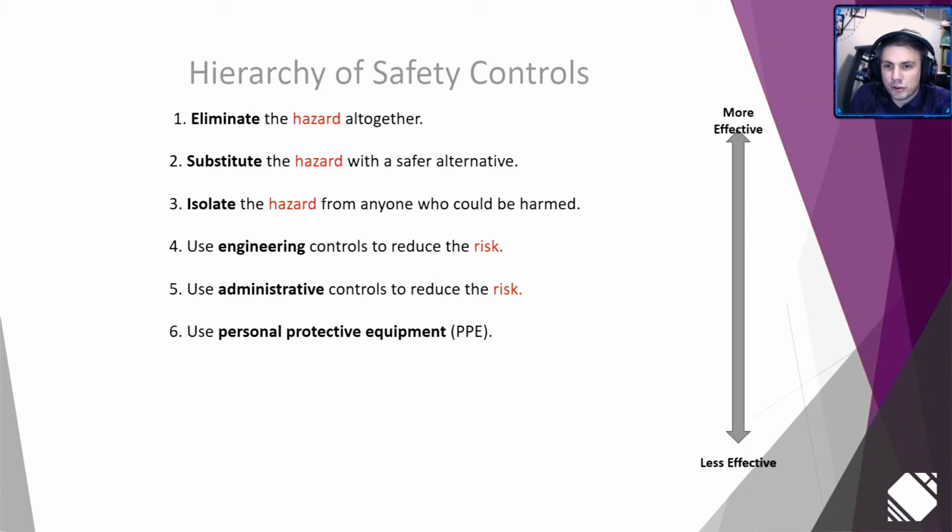And the last one is personal protective equipment. Something we do as engineers is called an arc flash study. You'll analyze the amount of energy potential inside of an enclosure so that if somebody's working in there, they know that they could be exposed to a certain amount of calories, it's called, which is just a certain amount of energy that could be blasting. And based on that, they know how much protective equipment to wear. The default being cotton clothing head to toe that's rated typically 8 to 10 calories, gloves, eye protection, hard hat.